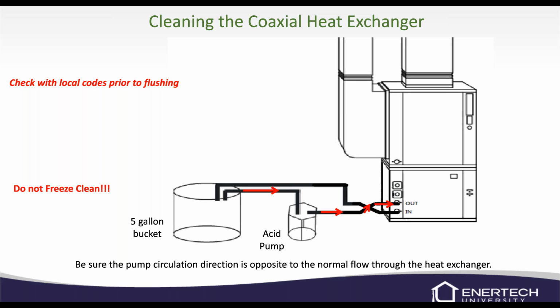And you may want to put water or some fluid with cleaner in there and let it sit for a little bit as well to try to break up some of the bigger stuff that may be stuck on there. But whatever you do, I would always pump in the opposite direction so you get some real turbulent flow throughout that heat exchanger. It'll help clean it a lot better.